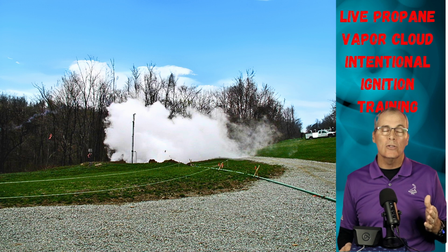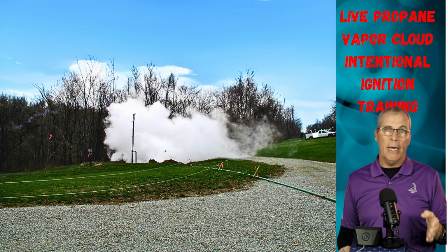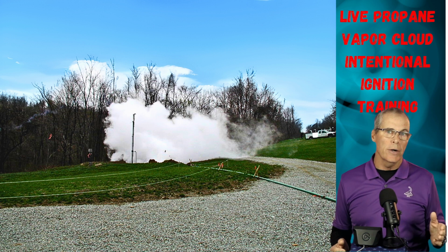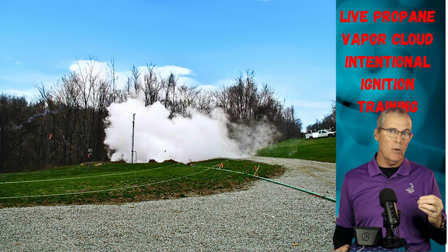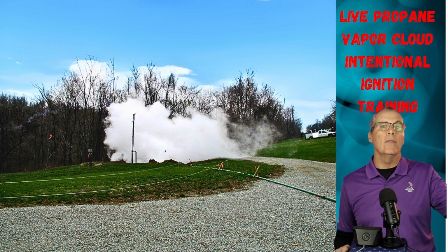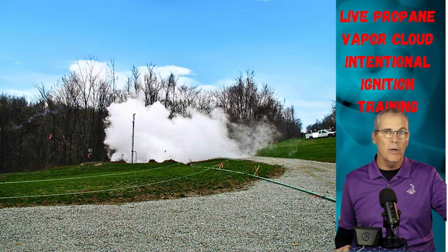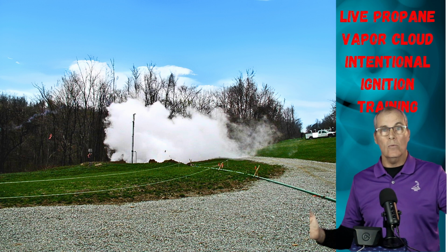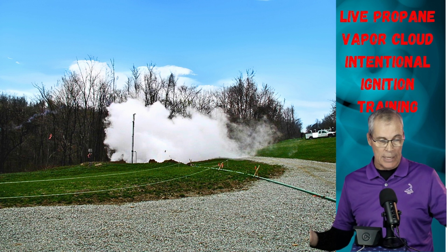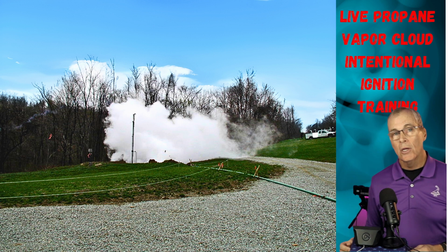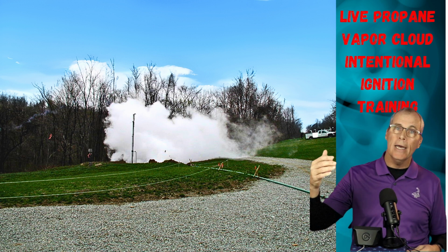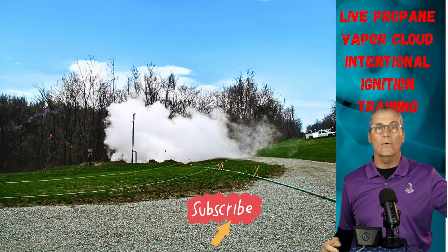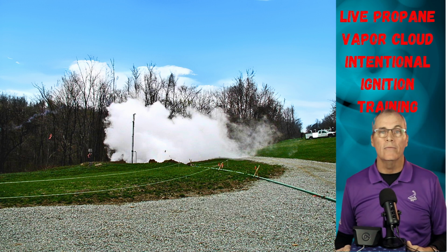Really, if they don't see the cloud start, we didn't want them igniting it. The idea was that they could only ignite clouds they saw start, and the reason they would ignite it would be that further down the valley would be a neighborhood or a community, and we didn't want to fill the neighborhood or that valley with propane, which could very easily happen in our large transmission system. So it would make more sense to go ahead and ignite it, have a torch fire, deal with a few burnt up trees, but not have several potential explosions and fatalities.